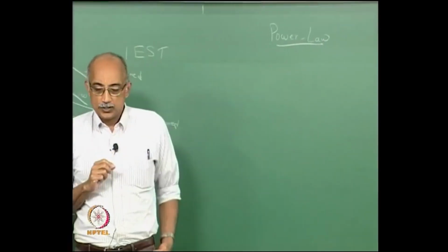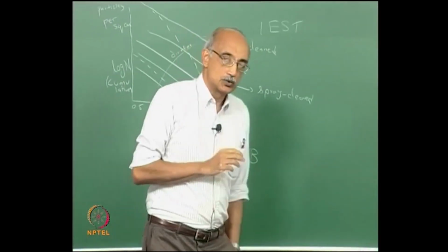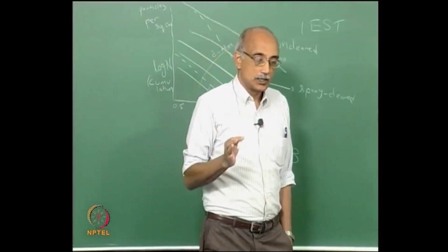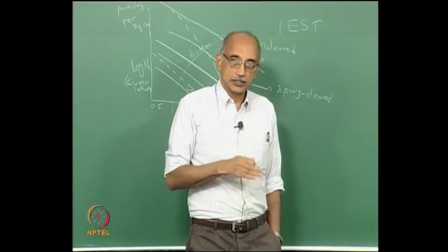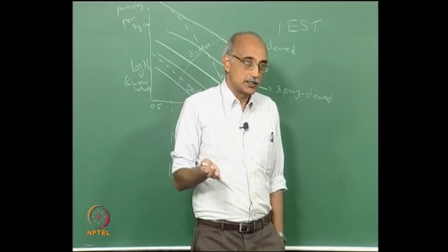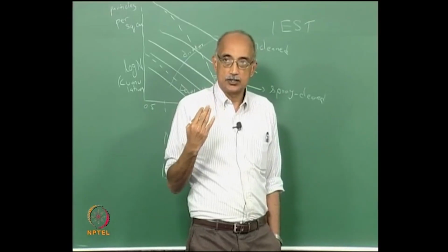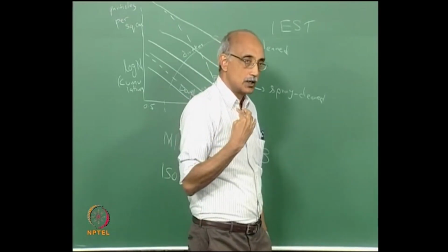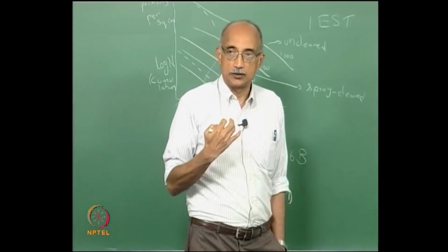A power law distribution is one that applies to environments that are actively controlled with respect to particles that are present in this environment. A classic example is a clean room, where you have filters that are designed to remove and retain particles from the air that is entering the clean room.